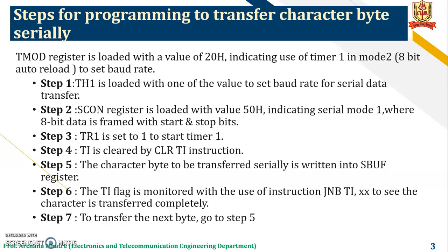Then the TI flag is monitored with the instruction JNB TI, label, to see that the character is transferred completely. And the last step is to transfer the next byte, then go to step number 5.